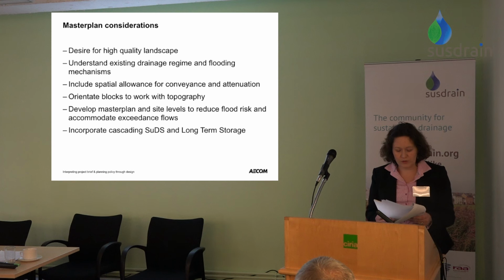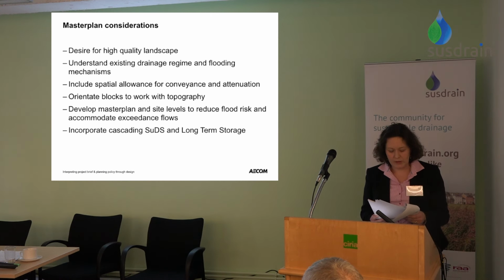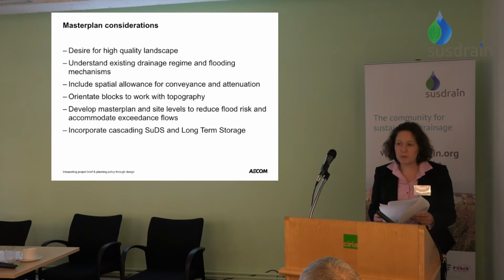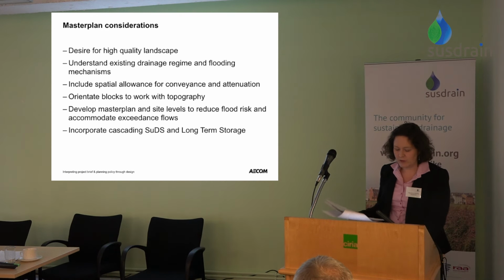We included an allowance within the master plan for conveyance of surface water and attenuation in open features. We worked with the master planners to orientate blocks to work with topography and consider exceedance flows. We worked with the landscape team to incorporate cascading SuDS, to provide a treatment train and restrict peak discharge leaving the site, and long-term storage to avoid an increase in the volume of surface water leaving the development.